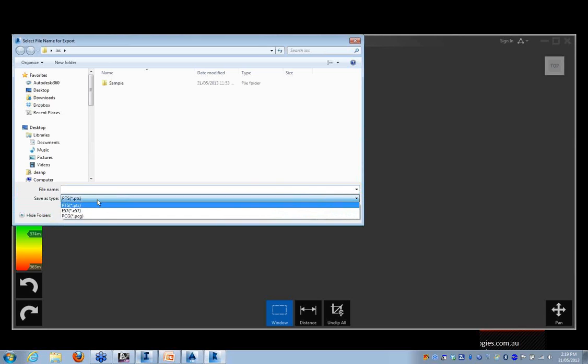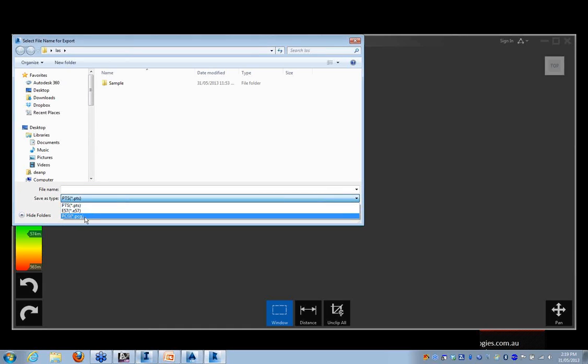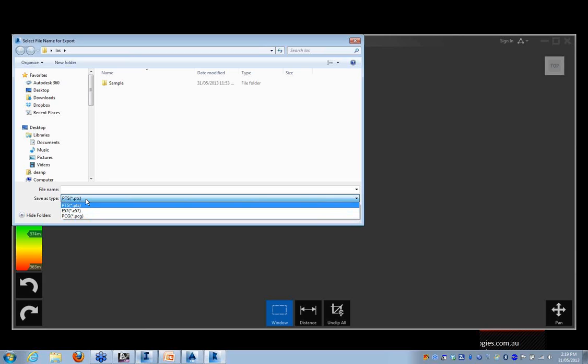Civil3D can read the PTS file in. Or in actual fact, if you make it from PCG, I think AutoCAD can read that in without doing anything else to it. It doesn't have to process it. So that's an option as well. PTS is just a points file, and then you can process that in a normal way in Civil3D if any of the other ways don't work. But I have tried them both ways and it's been fine.